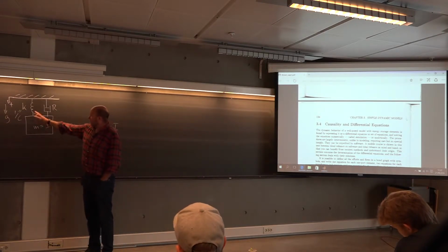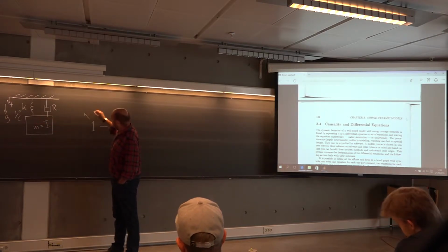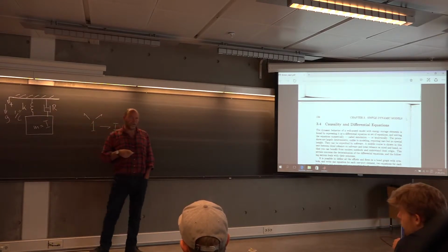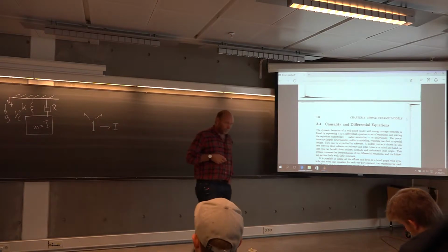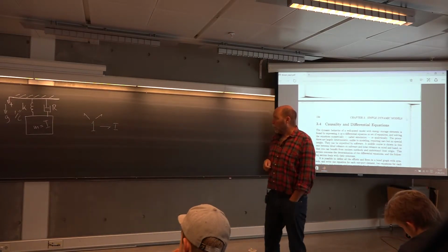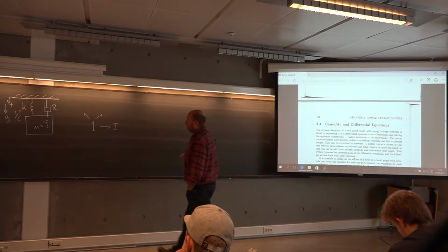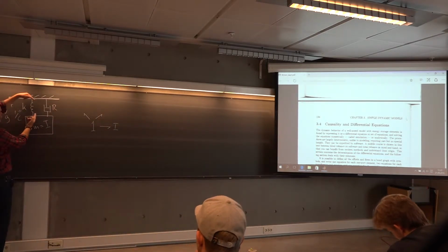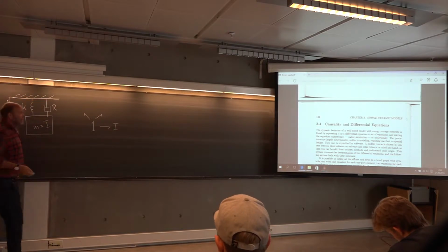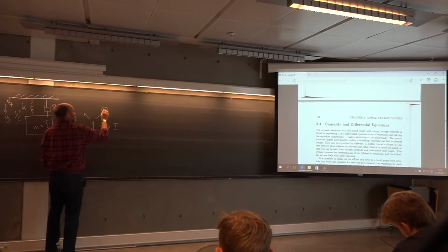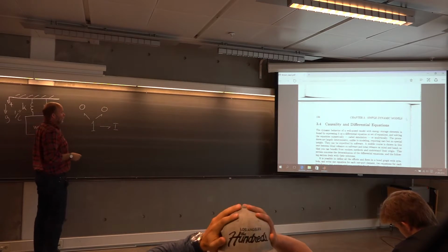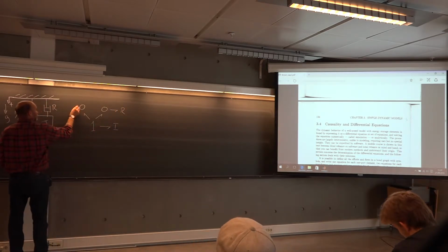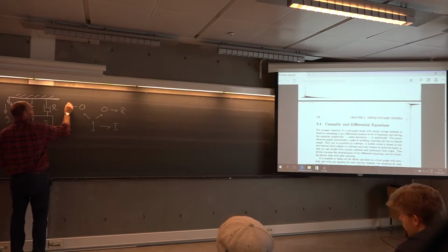Then he branches to a damper and a spring. How did we insert such elements? Well, it's the same force on each side of these elements. Same force here, same force here. Hence, you will insert them using a zero junction. So here you insert the resistance, here you will insert the spring.